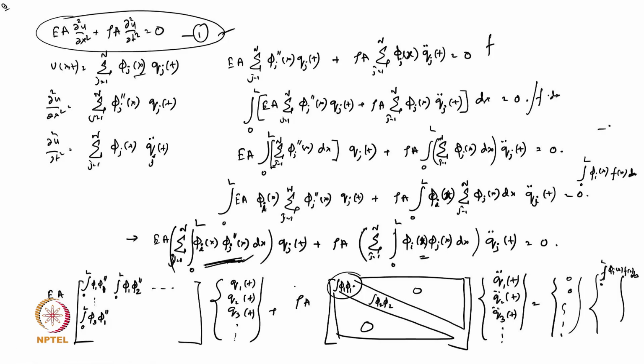Here you can put in any type of time function, you can give q(t) and also take q double dot (t), and solve it like a normal structural dynamics problem. You can use Newmark beta or Runge-Kutta, ODE solvers, all can be used here, because you will get a definite shape function, definite stiffness matrix and definite mass matrix, so you can solve it with the normal methods we discussed in numerical analysis.